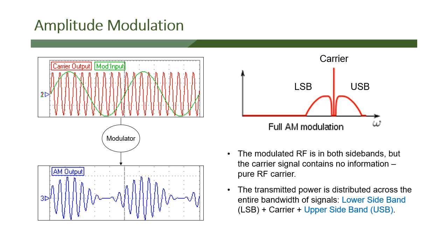When we do this idea of modulation, when the circuit that does the modulation is working, what we get is the carrier wave, the original wave, and then we get two sidebands, a lower sideband and an upper sideband. The carrier wave itself carries no information. Now remember, the carrier wave has been altered by the low frequency audio, and that's in the sidebands. But when we do this mathematically, which is what electronics is, all mathematics, we not only get the lower sideband and the upper sideband, but we automatically get a non-intelligent carrier wave, and that comes along for the ride. And so that's what an AM modulated waveform would look like on a spectroscope, basically.